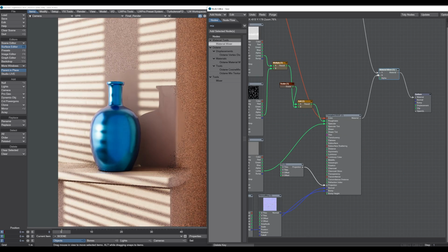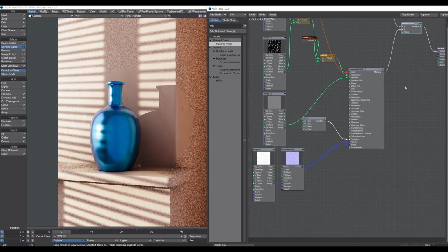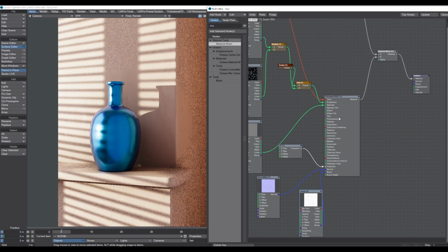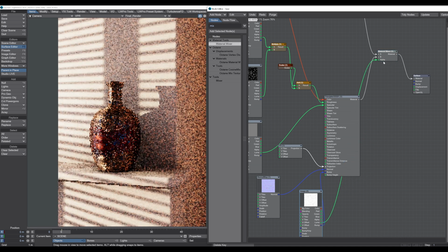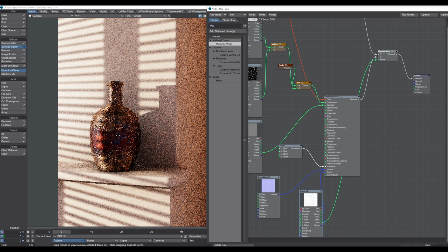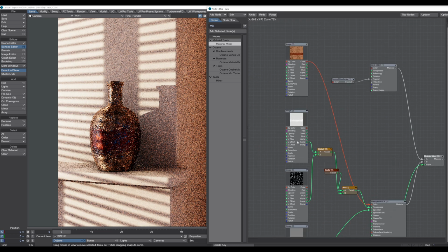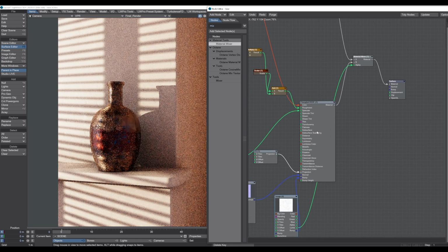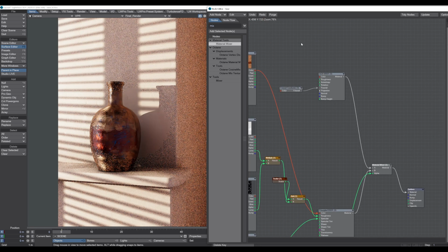And you can see that the A material component is dominant now, but what we want to do is use a scratch map as a mask to drive the A and the B material. So we use this Luma mask and drive the alpha input, and what you can see now is that we have this color map here for the first material, but only where the scratches are, this metal material shines through.